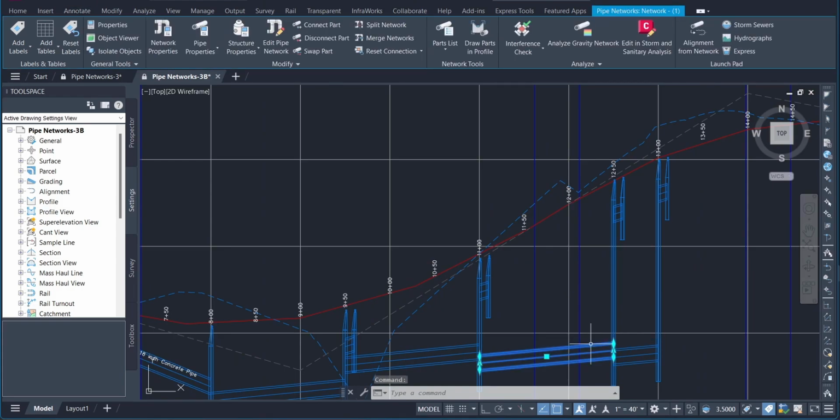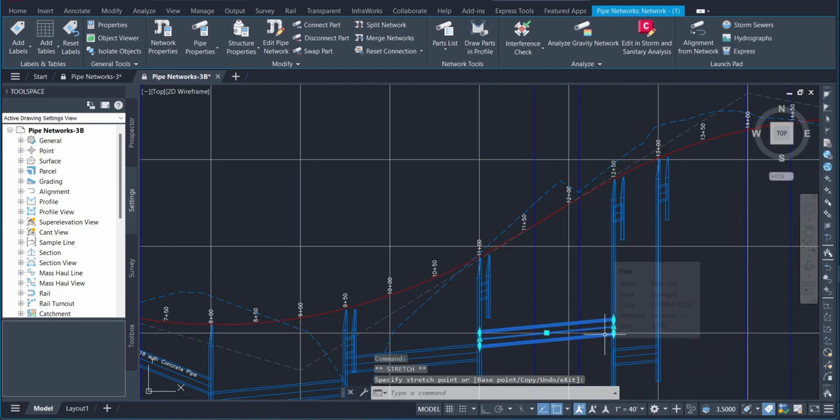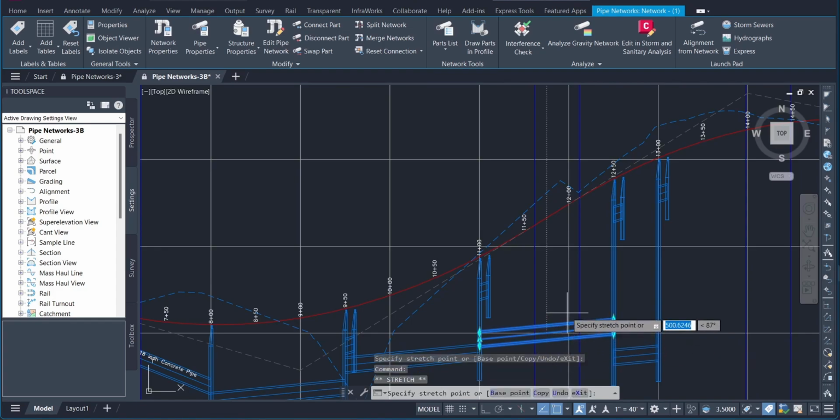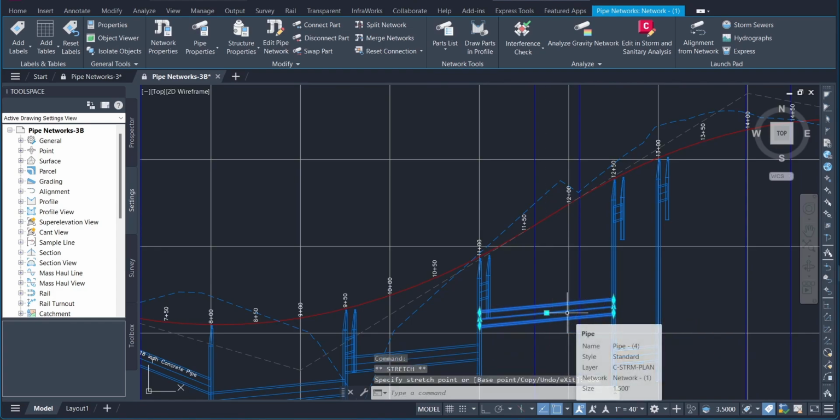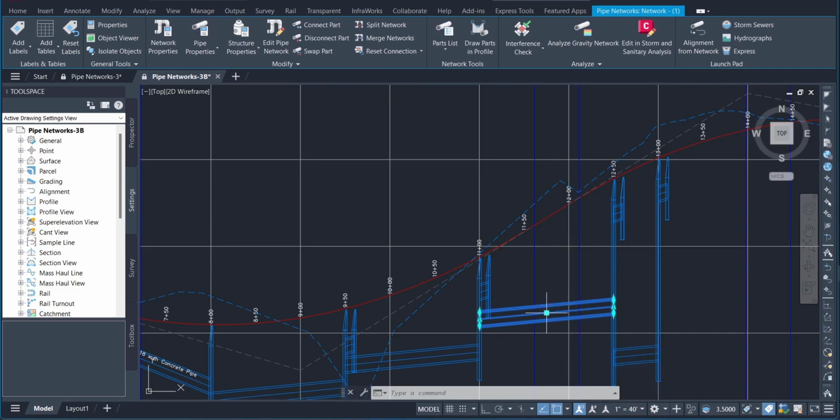In the profile view for Road 1, click Pipe, which connects the structures that are offset from stations 11+00 and 12+50 on Road 1. Click the square editing grip at the center of the pipe to make it active. Click a new vertical location for the pipe so the start invert elevation is approximately 650 feet. Note: the horizontal grid line immediately below the pipe indicates 650 feet. As you move your cursor, the tooltip displays the current elevation of the active grip.